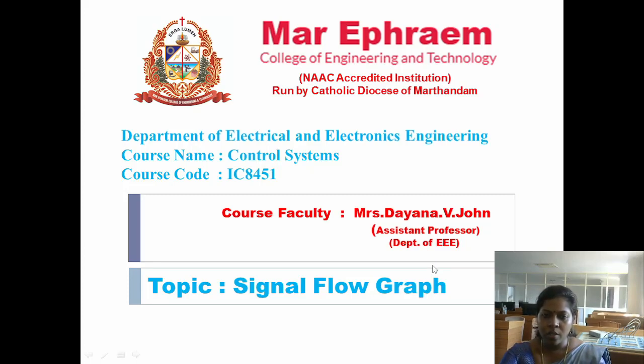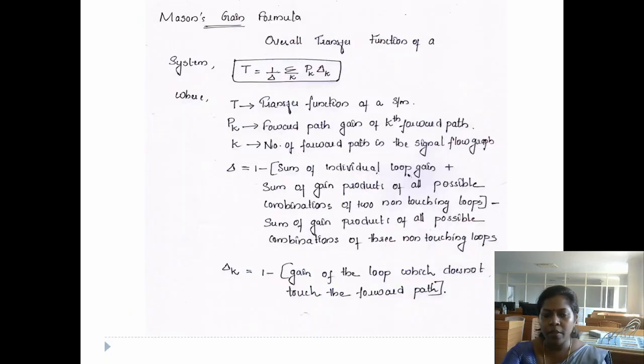Welcome you all. So in today's section we will see how we can find the transfer function from the signal flow graph. We will find the transfer function from the signal flow graph using Mason's gain formula. T is equal to 1 divided by delta summation k pk del k. So we have to know each term, that is what is delta, what is pk del k.